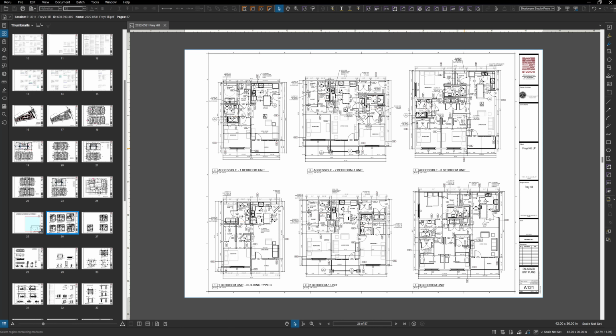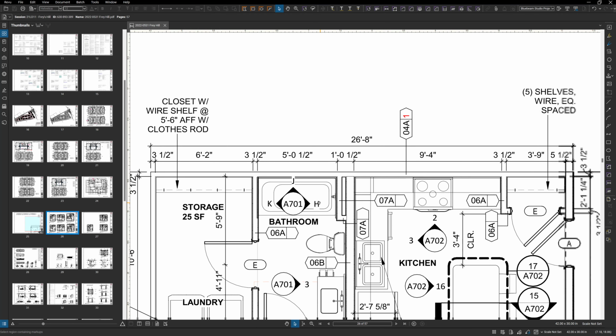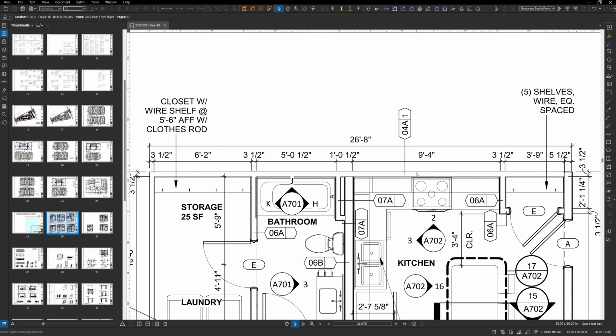What I do want to see is, when people do the units, sometimes they get into issues where things that should be tagged are not tagged and they need to be tagged. A lot of interior elevations, maybe a couple of missing walls. The other thing that I see sometimes, which again I'm trying to handle personally so that someone wouldn't have to, is missing the rough opening dimensions for bathtubs.